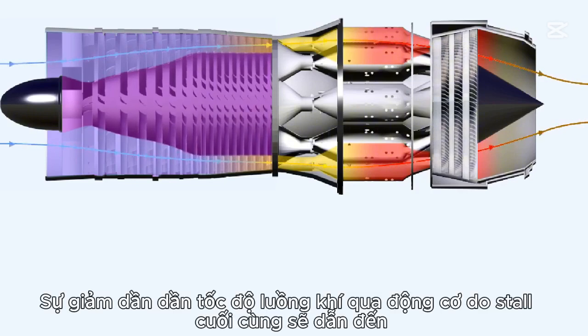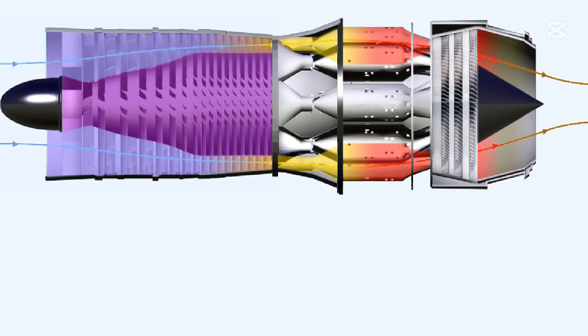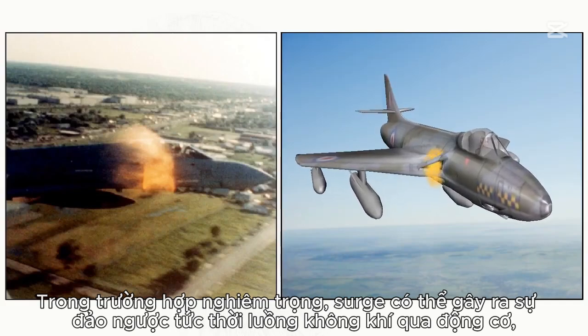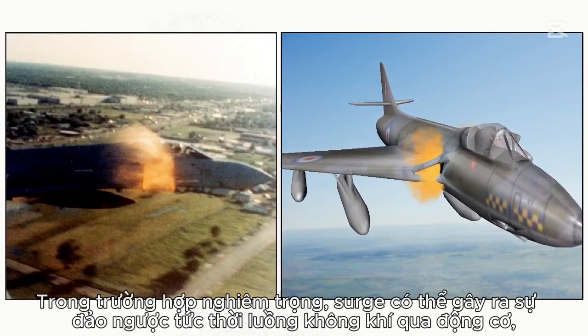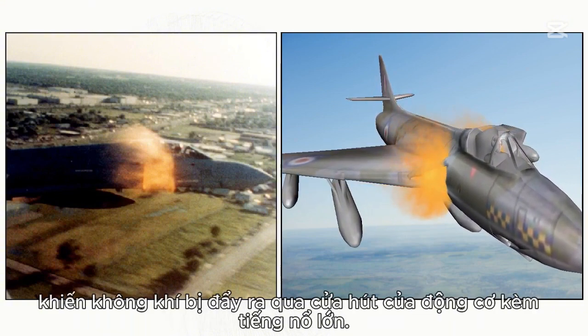The progressive deterioration of the speed of the airflow through the engine, caused by the stall phenomenon, will eventually cause a complete breakdown of airflow through the engine, which we said was called a surge. In severe cases, a surge could cause an instantaneous reversal of the airflow through the engine, with air being expelled through the engine intake with a loud bang.